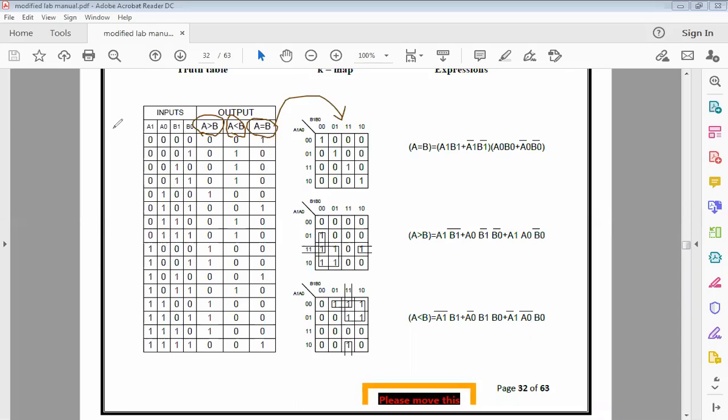Just make sure that you fill only where there are ones. Here we have a one at 0, and similarly here at this value, 5. So 0, 1, 2, 3, 4, 5. At the fifth value I will bring it up. Ultimately, whatever values are here will be filled into your K-map. You can look for grouping here, but since we don't group diagonally in a Karnaugh map, it's not possible for us. So ultimately we come up with an equation for a is equal to b.